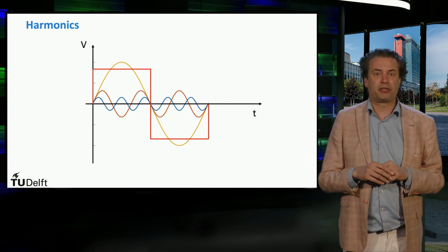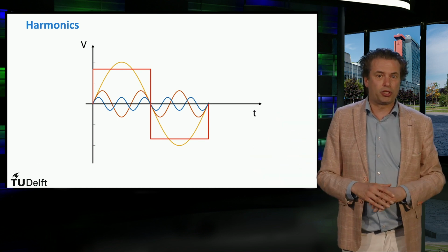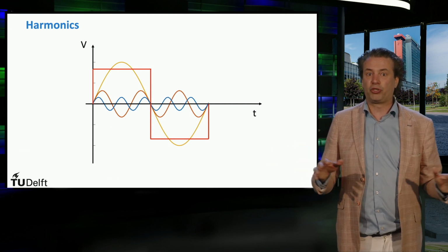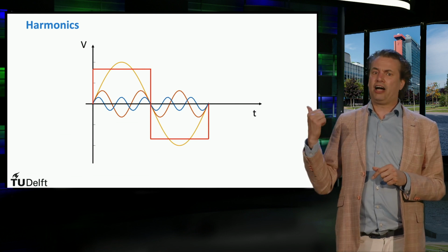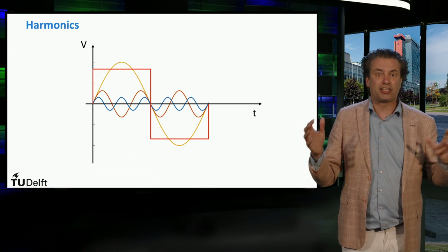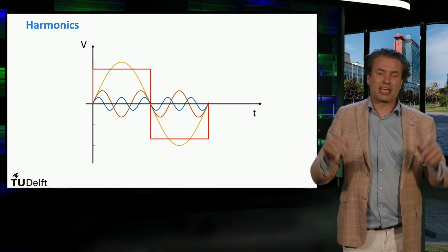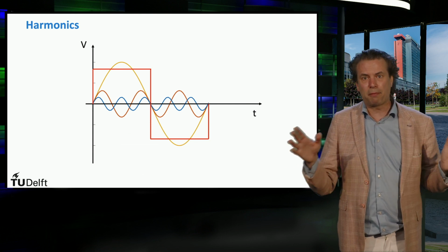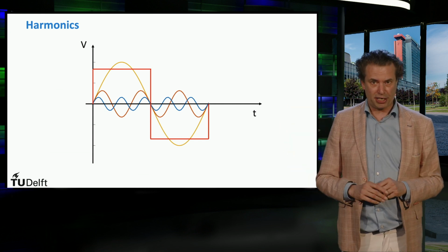Nevertheless, also superior harmonics are present and are injected into the system, contributing to the harmonic distortion of the signal. All electrical appliances and generators produce harmonics and are therefore regulated under standards. In large volumes, these harmonics can add up, causing interference, malfunctioning of devices, and even fires. In order to reduce the harmonic content, filters can be used. Filters use capacitances and inductances either in parallel or in series to cancel out the lower or higher harmonics from the output power.